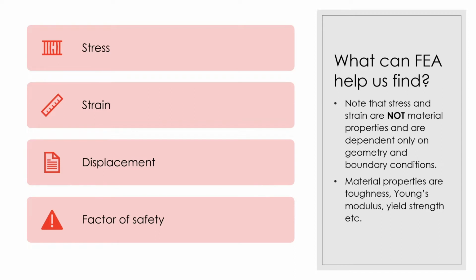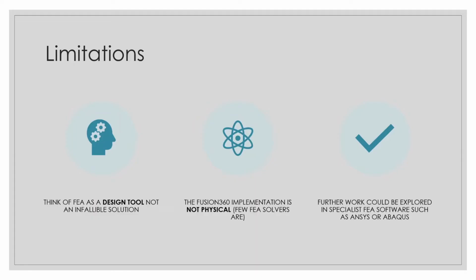Then you can do your own research on what kind of material properties your print material, maybe PLA, has, and you can make some decisions based on that. There are options to pick particular materials in Fusion, but as Fusion might not know exactly how everything's layered or what kind of infill you're using, you might not get very accurate results. So that's just a consideration for you.